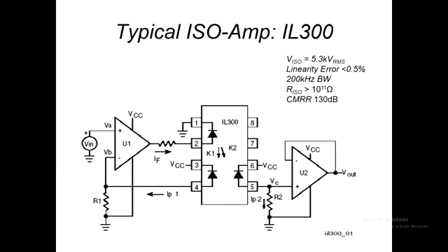A unit that some students have used for projects before, that isn't as expensive as many of the others, is this one. That's a company called Infineon, I think, made this, and it needs some linearization. As you can see here, there's that extra diode presented at the input, and it gets illumination from the LED just as the receiving end does. There's this compensating diode in the input circuit as well to, if you like, pre-compensate, pre-linearise the signal.